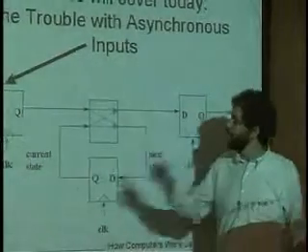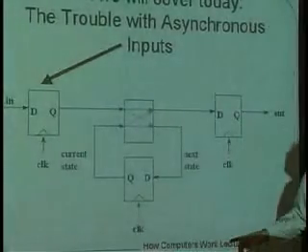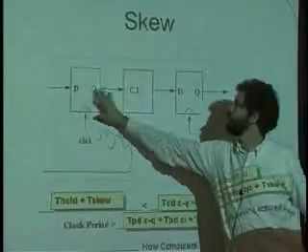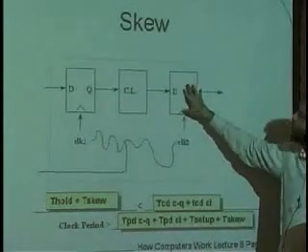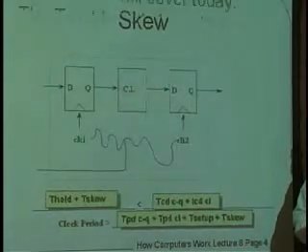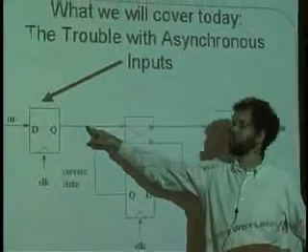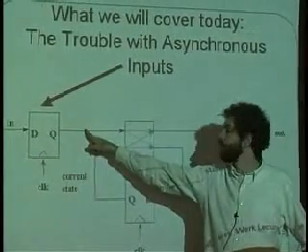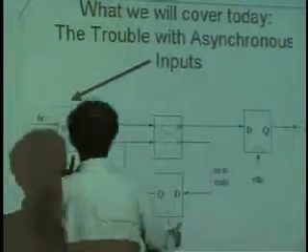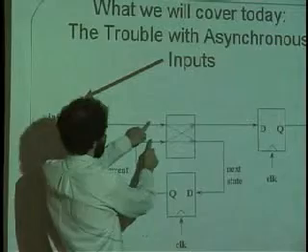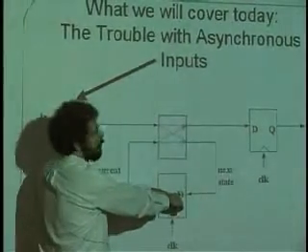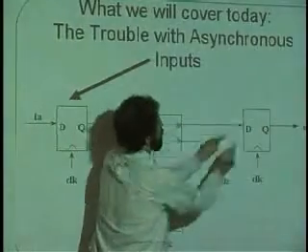And here's the idea. I know from the previous diagram, the unwrapped loop, that if I set up a chain of a register and combinational logic and another register, that I can go ahead and clock these all at the same time and I'll obey the timing constraints. So if I have a problem with the timing constraints on this wire being bad, I'll just put a flip-flop there, and since I clock this one and this one at the same time, when the clock goes off on both of these, the amount of time it'll take the data to get here will be the same, and so therefore I will meet the setup and hold times going into here. And the same way going out to this output register over here.